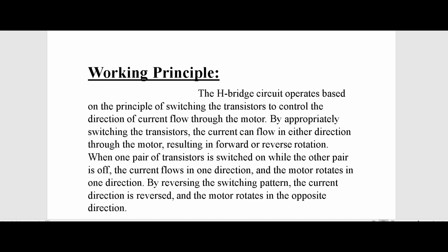Now, what this paragraph is saying is that the H-bridge operates on the principle of switching. Switching of the transistors is used to control the direction of current flow through the motor. The transistors control the flow of current that will pass through the motor. By making the appropriate switching steps, the current can flow in one direction or the other direction through the motor, making the motor rotate in forward or reverse direction.